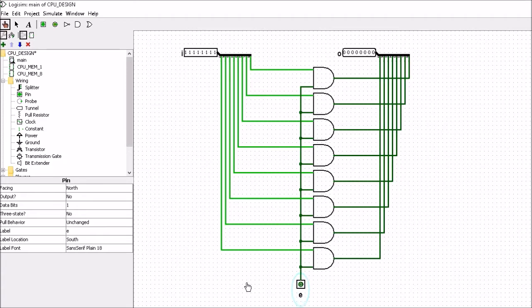What we say is the set writes to the memory location and the enable reads from the memory location. So the set places information into the memory byte, and the enable passes that information from the byte onto the bus or some external part of the CPU.